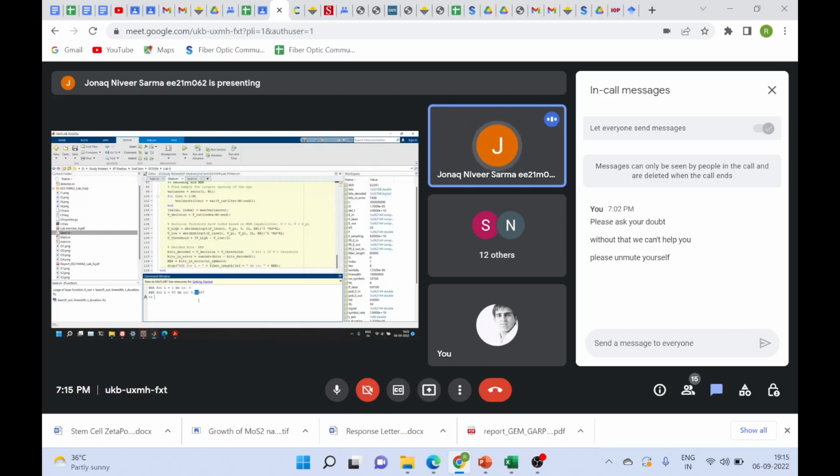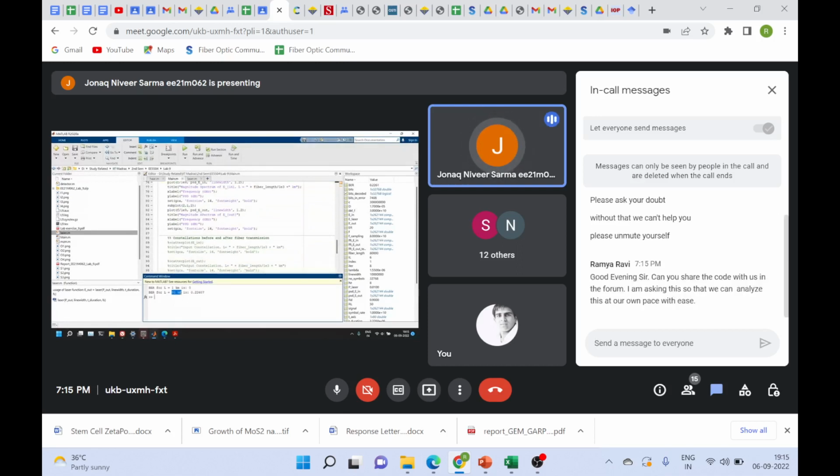This is completely unacceptable. I think link design is coming at week 8. You will see we can tolerate one error in 10 to the power 9 bits. So this cannot happen in a link that we are using. But our span lengths are 80 kilometer, 40 kilometer, 80 kilometer, that kind of range. So we will have to transmit at this range, but we have to compensate for the dispersion. We can use dispersion compensating fiber, or we can also use digital signal processing for this.